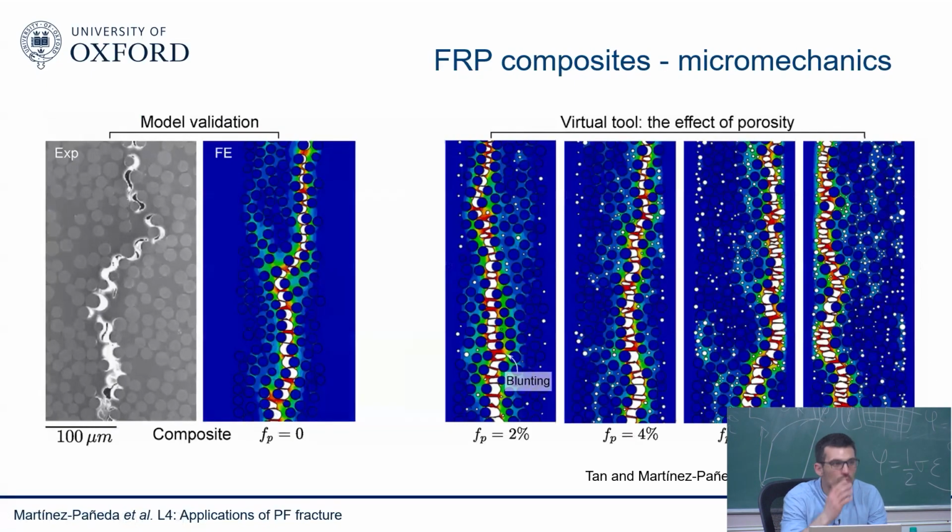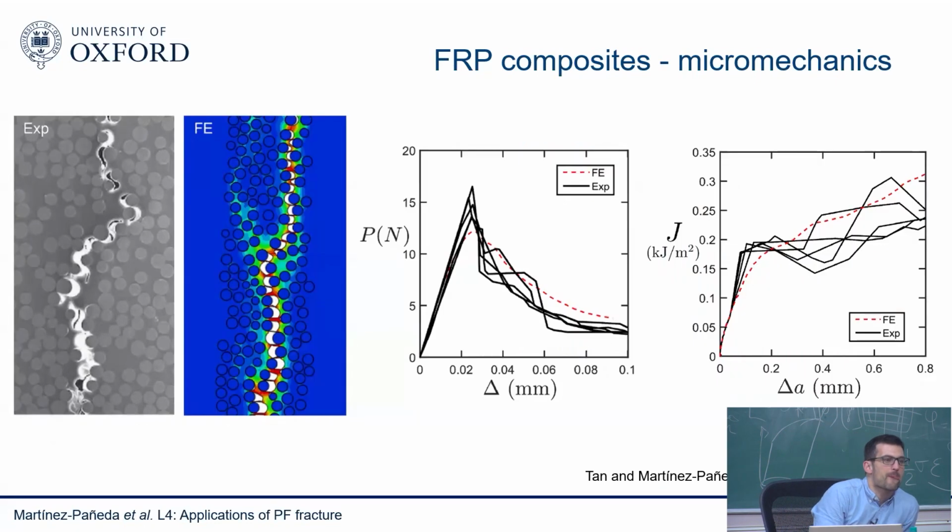And then what we can do, yeah. So I'm just curious, did you take the image of the composite and mesh it as is, or you just assume that it's a random arrangement of the fibers? We did random arrangements of the fibers, and then we look and see whether it was similar to that. Not the image-based meshing? Yeah, because they also did multiple tests and so on, so it's not identical, but it's similar, I would say, yes. So I think we ensure the same fiber matrix composition, so the same volume fraction of fibers, basically. Yeah, and then same dimensions of the fibers and so on.